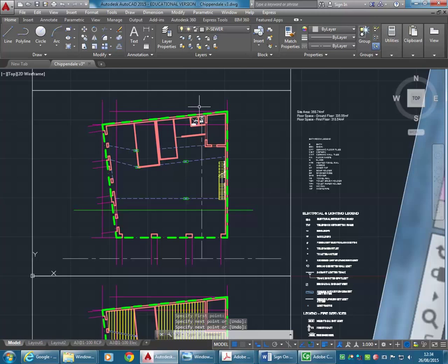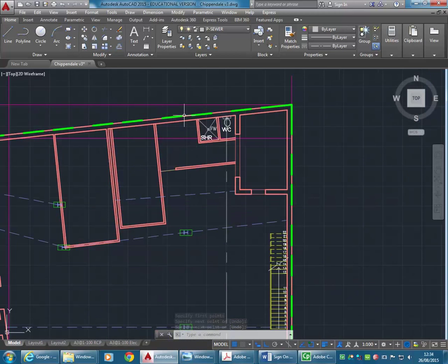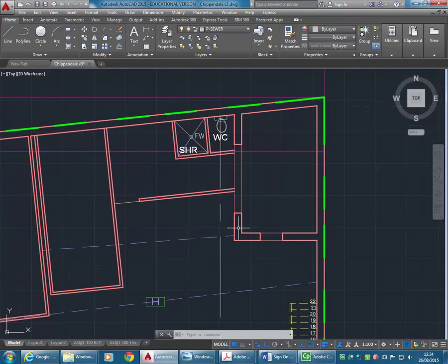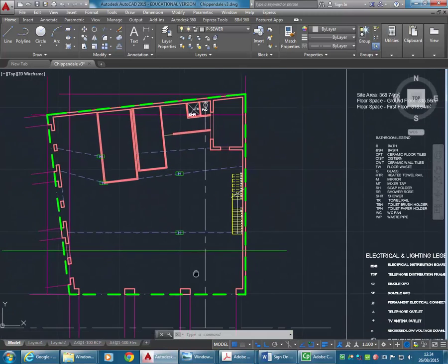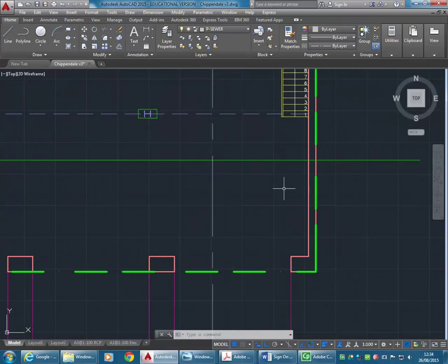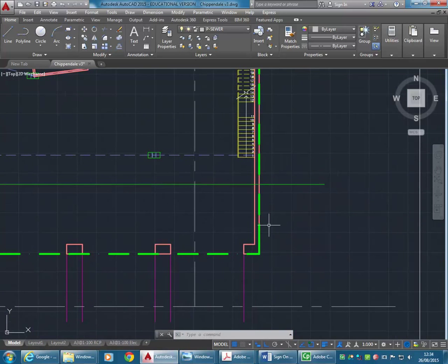And so when you're doing your new design, you can either connect to this existing sewer connection and have your bathrooms in the same place rising above, which would be fine if they're stacked on top of that area. Or if you've got them up against this light well, you could probably have the sewer pipe running outside there and connecting to this area. Or if you have it in this vicinity, you can have it draining out through this wall and have a riser that comes down alongside that wall and then just connects in that way.